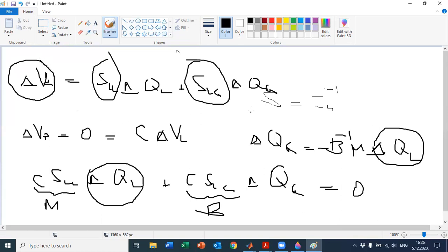So basically, when these changes in the reactive power of the loads happen, there exists a question of whether our generators have enough reactive power reserve in order to smooth out and neutralize these voltage deviations. And the goal is to find those pilot points which, if we control the voltages in those points, then the voltage deviations across the whole network will be normal.